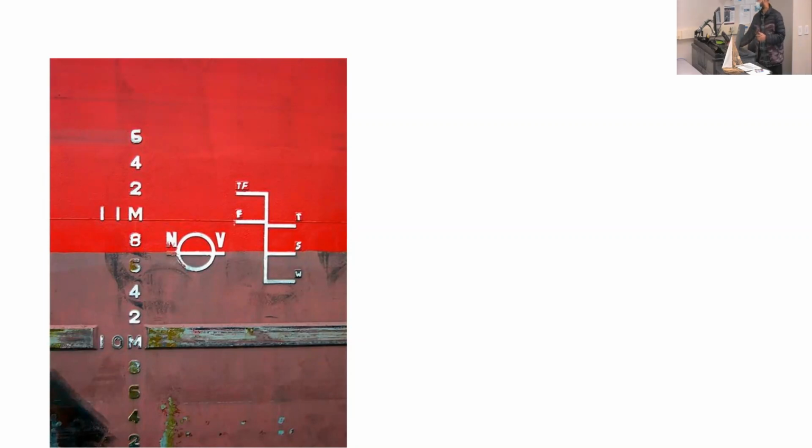So look at the markings. If you start sailing at this level from New England, you just keep going and you'll see the ship changes its water line to this. So does it make sense? As it starts sinking, it's displacing more water. Weight of the water depends on volume and density. Density is lower, so you need to displace more volume. All right? So that's the main purpose of this.